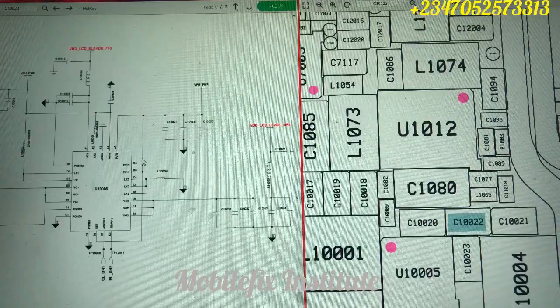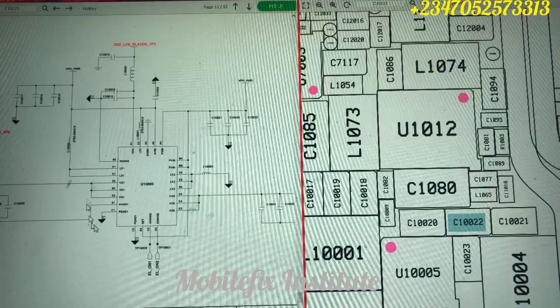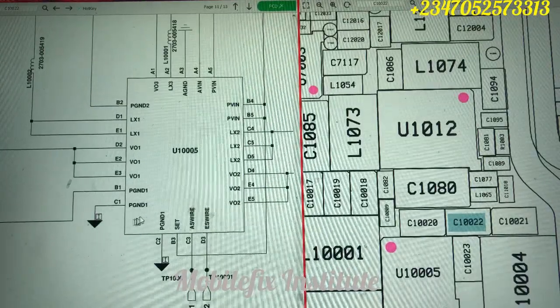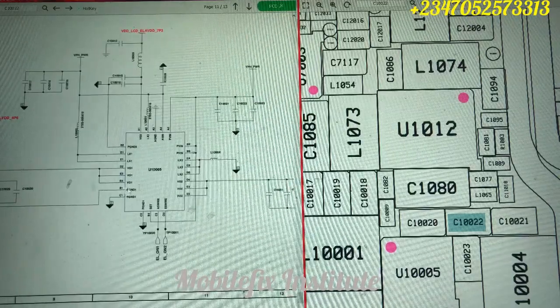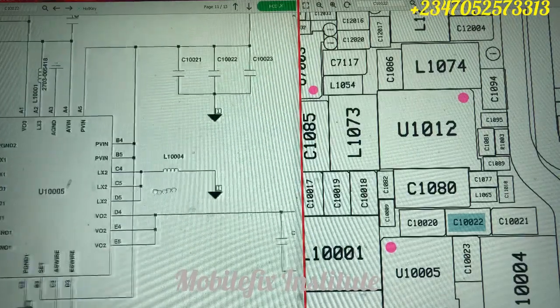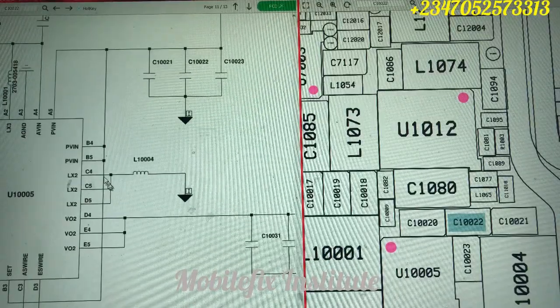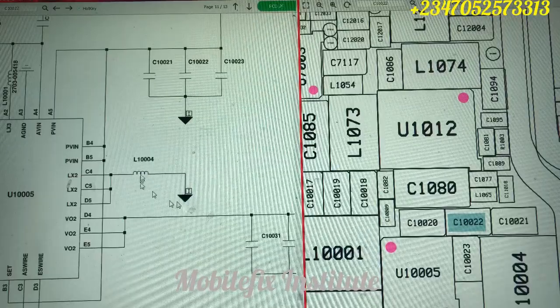So as you are troubleshooting, when you get to the point that you've not seen the fault, when you lift your display IC, test the connectivity of this VPH line. If all of the VPH lines that enter this IC are connected, because if one ball or one line is open, one VPH line is not receiving VPH voltage, that means your phone will not display.